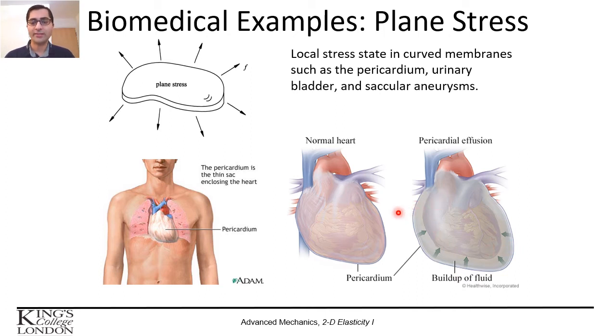Here we can just slice a thin plate from the whole geometry and assume that body forces due to the weight of the fluid and boundary tractions due to the pressure of the fluid are all aligned with the cut plane, and assume that there is basically no normal pressure or force normal to that cut plane.